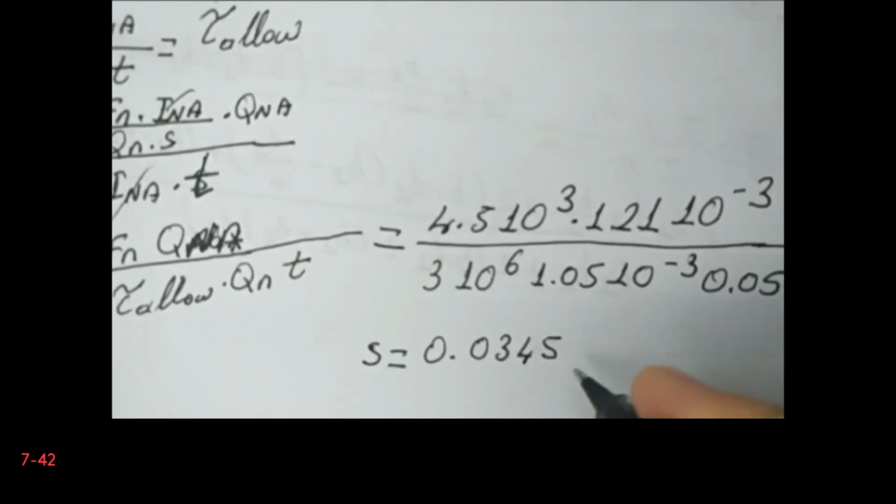Now, in fact, S is wanted to be multiples of 5 millimeters, and therefore if we use a distance of 35 millimeters, this means that the nails will not be able to carry the load because it will exceed their allowable shear force. Therefore S is equal to 30 millimeters. So this is the answer of the question.